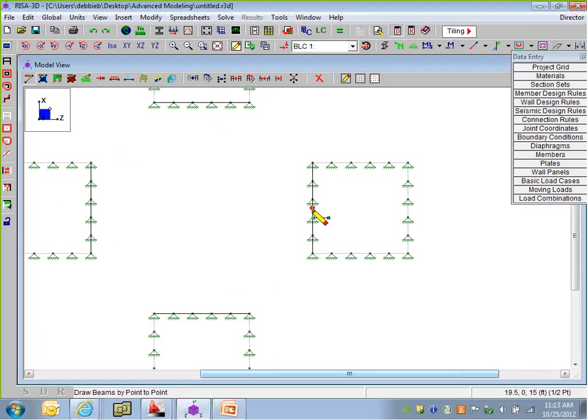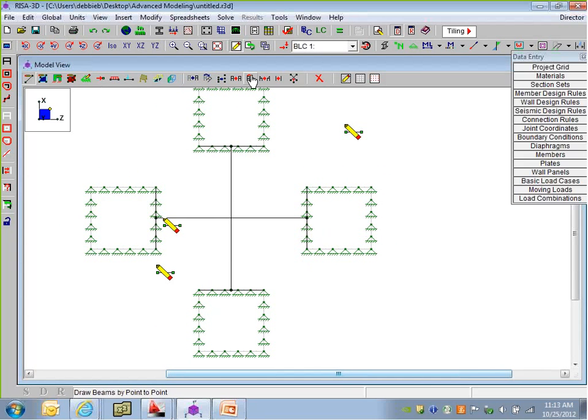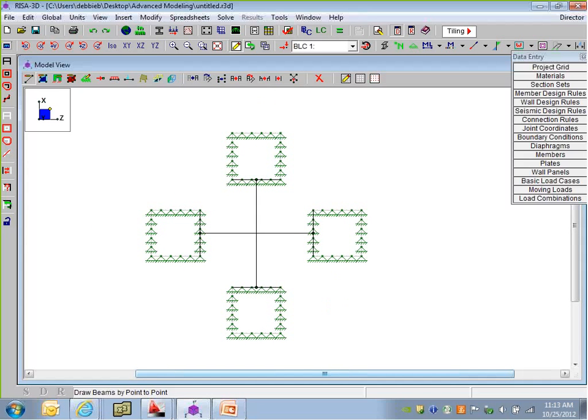If you look at the bottom right corner of my screen, it says half point. And that tells me that's the half point of that beam there. And I can cross all the way across to the half point of that one, and I can draw all the way across to there, just making sure. Now, if you had an odd geometry, mine's very symmetrical, this would help find where a center point might be. So you could find that a little bit easier.